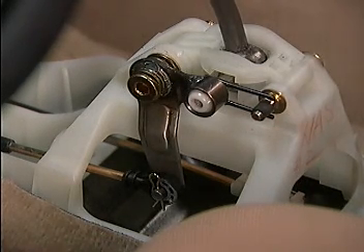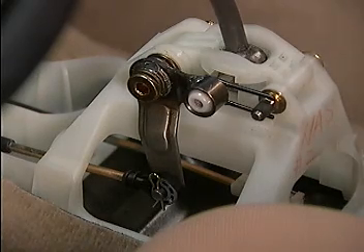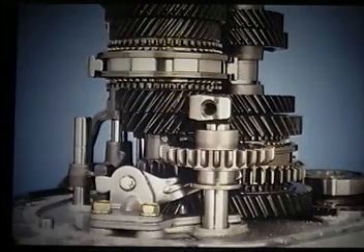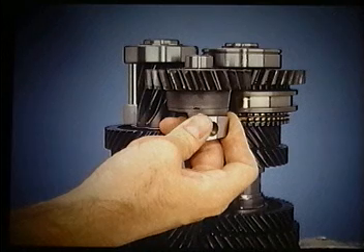Power flow through the transaxle is similar to the F5MC1. The F5M41 uses a sliding reverse idler. The F5M42 uses a constant mesh reverse.